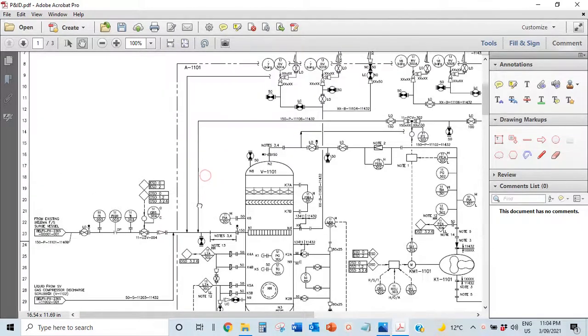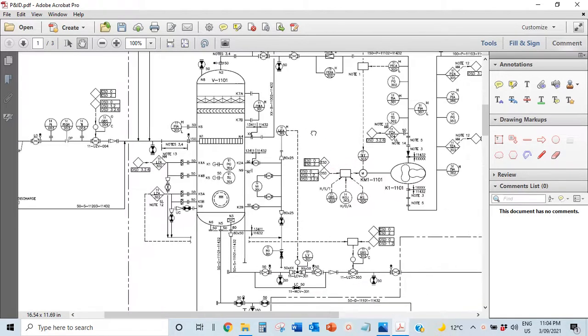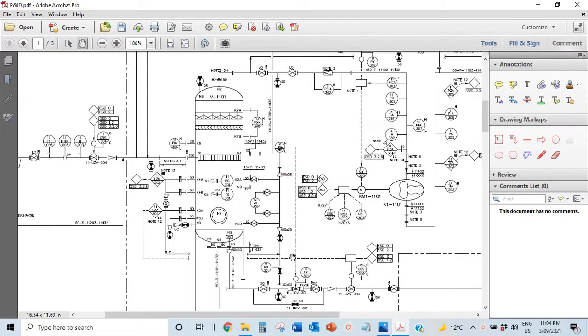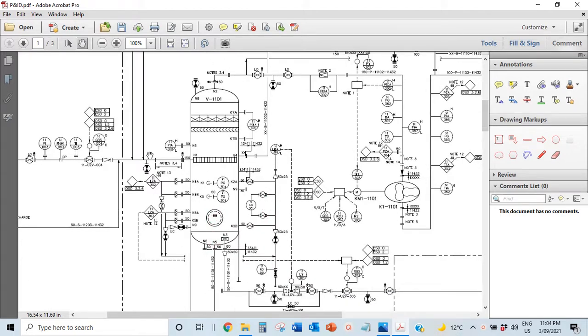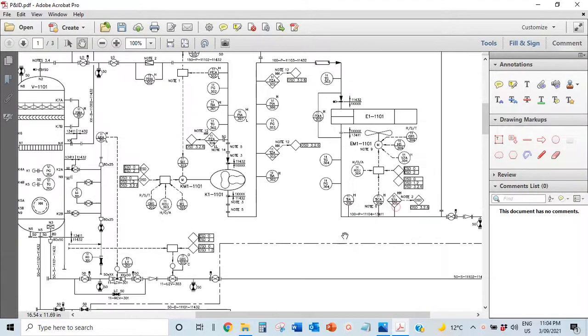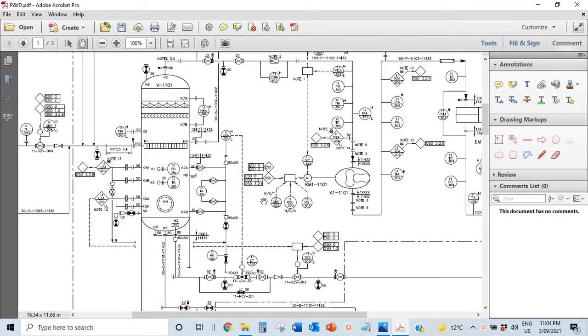In this one we're going to be marking up isolatable sections, and that's why the video before this is talking about depressurization and blowdown. What we want to look at is, on fire detection, when your shutdown valves close and your BDVs, your blowdown valves, open up, what's the inventory that is locked in here? And what's the risk that we can get out of that isolatable section? We want to have an idea of how much liquid and how much gas is going to be trapped in the system.